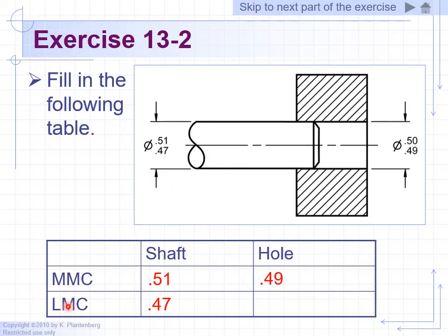It'll have the least material condition. It's also at its lightest. And obviously for the block, we'll have less material when we drill the largest diameter hole allowed. So the larger the hole, the more material you're removing, and you're left with less material in the block. Okay, so the LMC, least material condition for the block, is when you drill at the maximum allowed diameter.